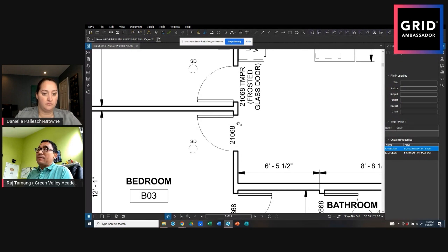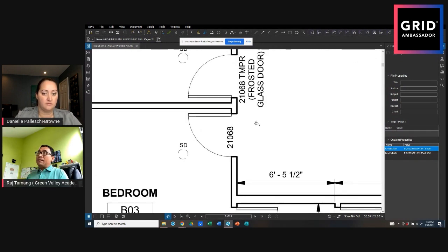The way to find out is, let's say this side is the hinge. So this is the hinge side. You go and stand here, facing this way. That's how I do it, an easy way to find out all that right and left and in and out. You stand here and look this way, so now your right hand is on this side. So this is a right hand door, and it's swinging inside, so this is right hand in-swing.